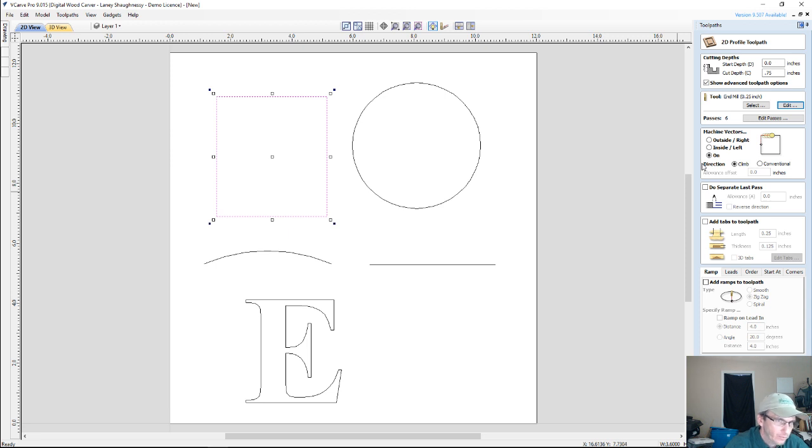Now, as a default, we're always climb cutting, but when does the occasion for conventional cutting come into play? That's what you want to know. It may have something to do with grain direction. We're getting a little bit too much chatter in a climb cut, so we need to do a conventional cut for a cleaner looking cut. It could have to do with the prevention of tear out or chunking, but also increasing or decreasing our chip load.